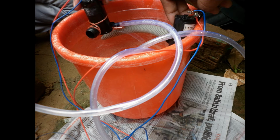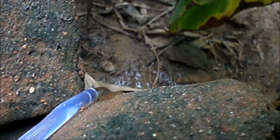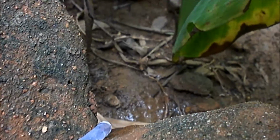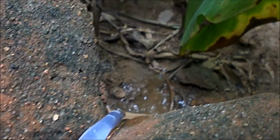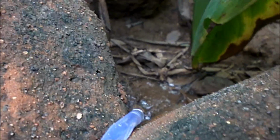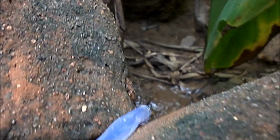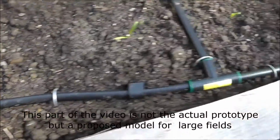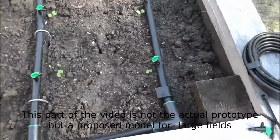The actuators used are two separate 12-volt DC pumps for the drip and the sprayer system. When the soil moisture level goes below the set value, the drip system is activated as shown here. The reason for having a set value is that the actuators are not turned on for small changes in the moisture level or for the humidity or temperature. When the drip system is actually set up in the agriculture field, it will look something like this.